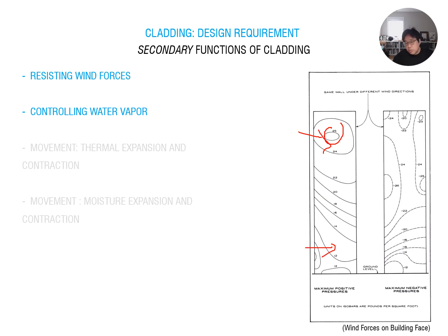Depending on this wind pressure, you have to provide a different window frame type and consider a different window size. Higher pressure, of course, has to be given a deeper window frame, right, to hold the window panel tightly from your exterior design to resist these high wind forces.